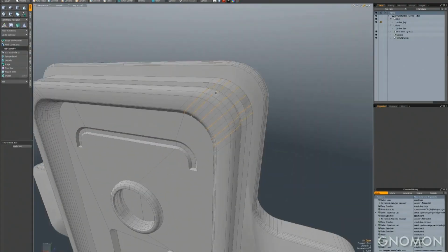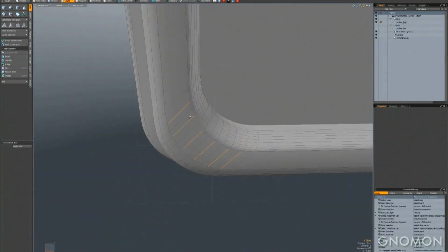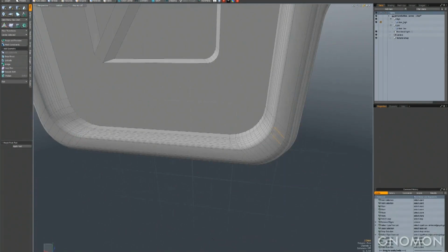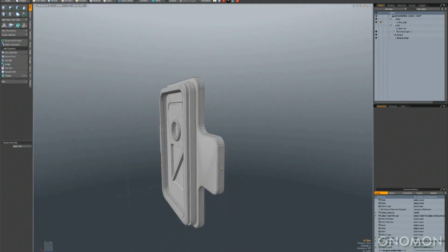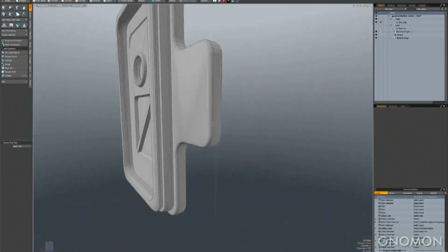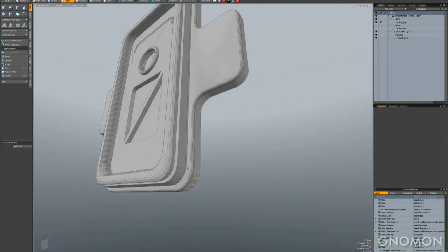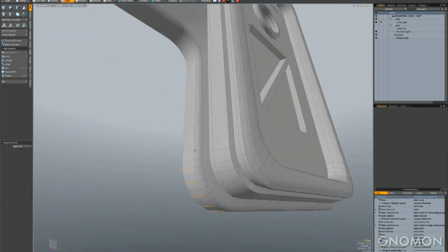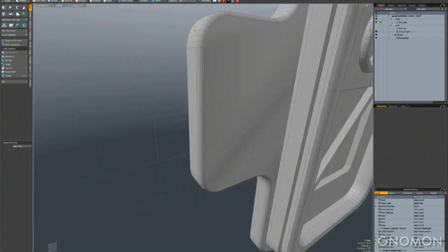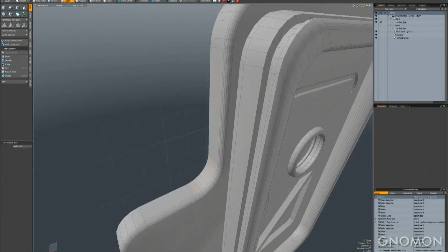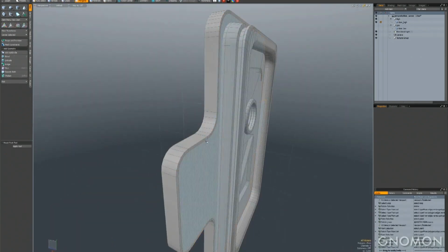I've taken the door out of that rendered example, and we're going to use some of Modo's selection tools and other tools to see how we make a low-res version of that and bake that geometry down. What you're seeing right here is the high poly geometry. It's just a bunch of bevels. Right here we're using Modo's Step tool, which selects the next logical step after two components that you've selected. It's great for creating low polys too.